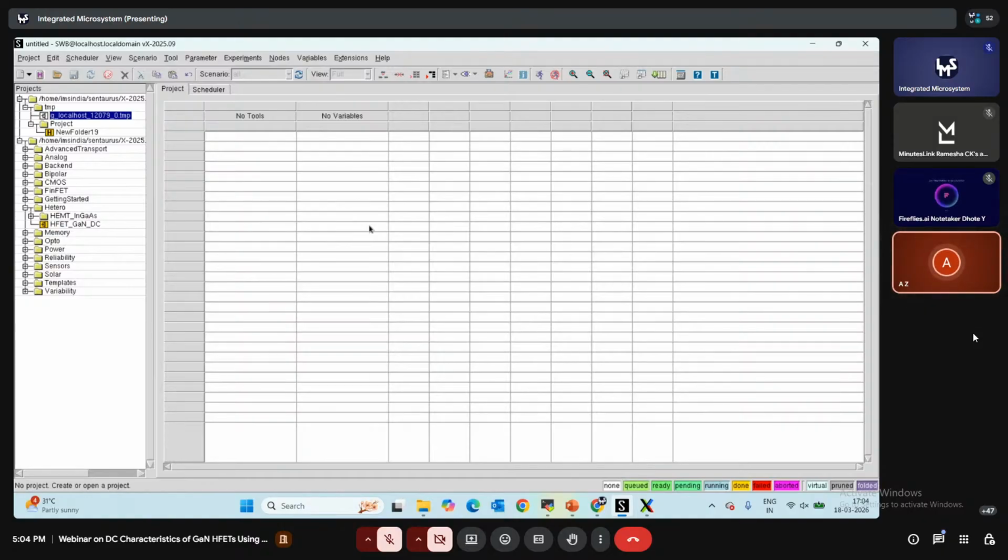If you are using aluminum again, then that would change the work function itself. There are various papers defining the work function for a particular thickness of metal. Whatever you are using, there are experimental values available for that. For that we need to do it, because there we are using a combination, like the uppermost layer is gold for insulating this, and the lower are titanium, Au, and the combination of these.